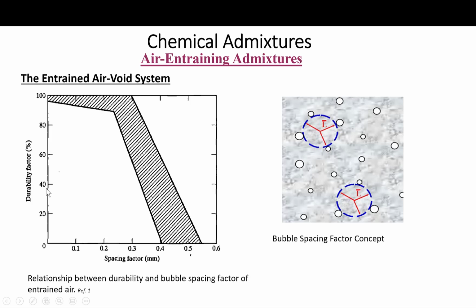Durability factor, an arbitrary value, and see how it's impacted. As we increase the spacing factor, the durability factor decreases, and as we said, for satisfactory performance it should not exceed 0.2 millimeter, something around that range right here. But as you increase the spacing factor, the durability factor decreases. Keep that in mind.